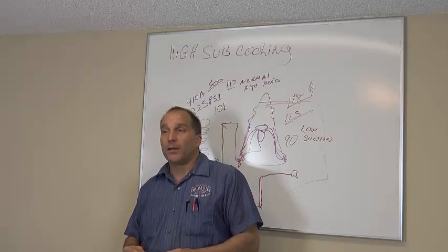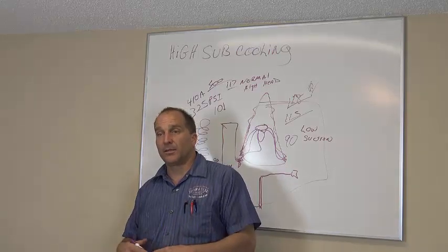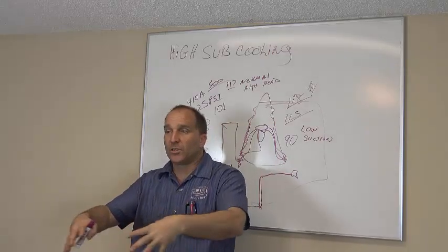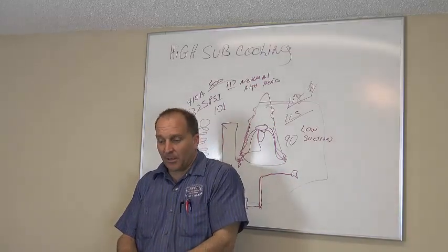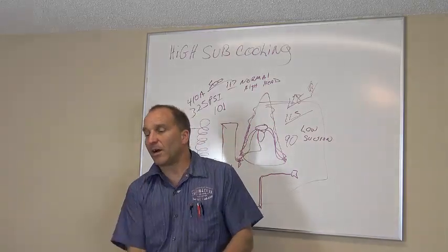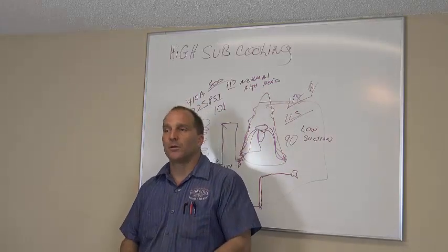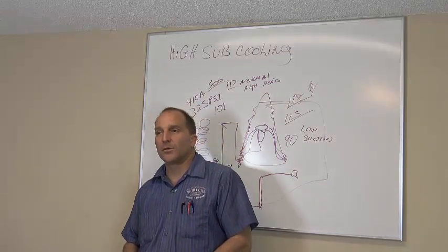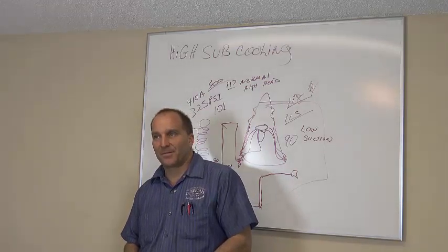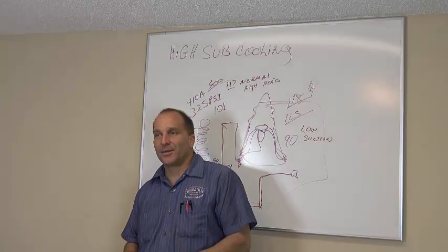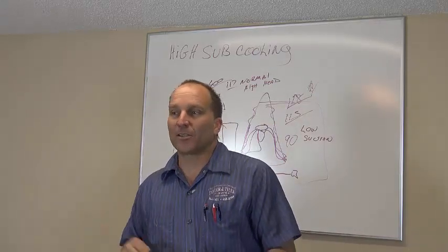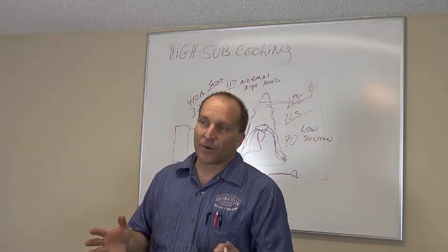What if a dog continues to urinate on the condenser coils and corrodes them, and they're clogged up a little bit at the bottom, but they're falling apart in some seams and you only have the copper lines running because the aluminum's all messed up? High subcooling or low subcooling? It's going to be low, because you're not getting everything across. It's not transferring the heat properly. You've got to remember, the aluminum on those condenser coils is actually transferring heat.